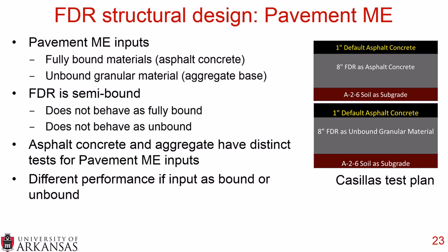And that is what Dr. Sadie Casillas did toward her master's thesis. Because asphalt concrete and aggregate have distinct tests for Pavement ME inputs, Dr. Casillas took the exact same material, the exact same full depth reclamation, and ran the asphalt concrete test. And that is the schematic on the top. Then she took the exact same material and ran the unbound granular material test.